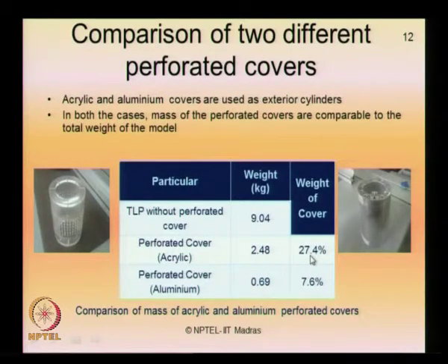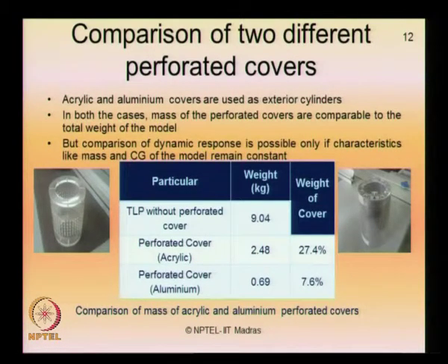Therefore, it is not a good practice to have a heavy density material as an outer cover in practice as well as in experiments, because one must match more or less the mass ratio between the materials, at least between the inner and the outer cylinders, because it is essential that the comparison of dynamic response is possible only if the characteristics like mass and CG of the model remain almost constant.